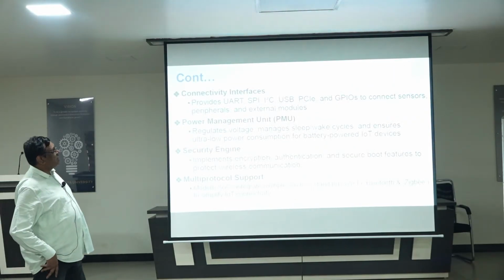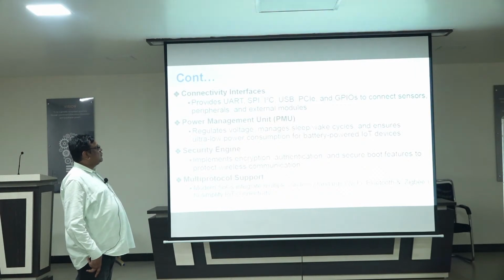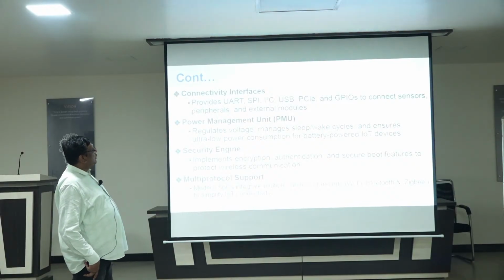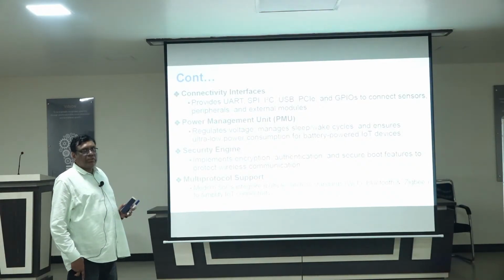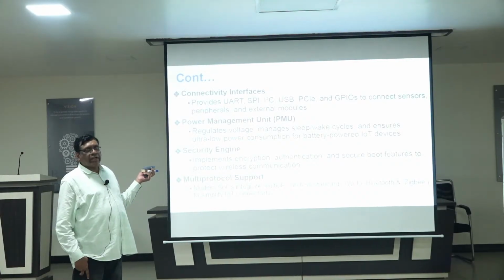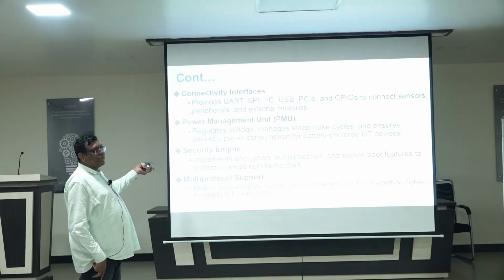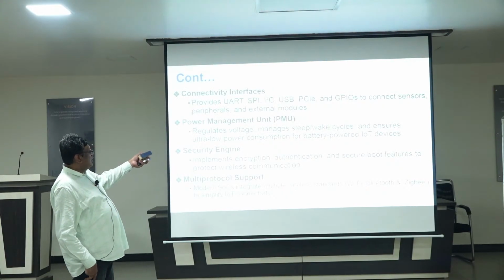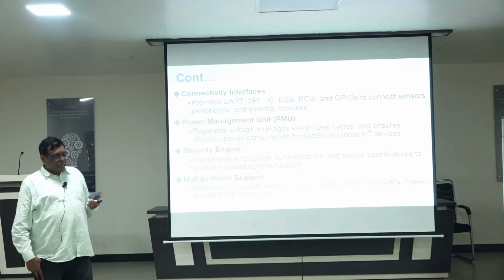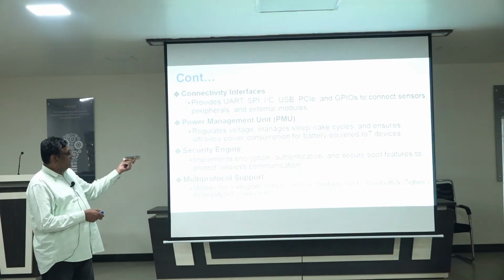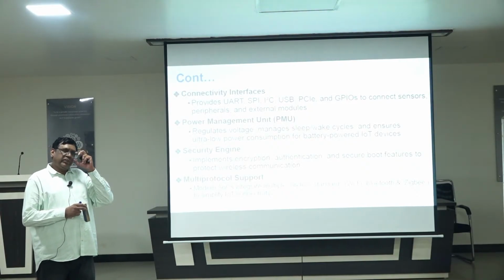Then connectivity interfaces like I2C, UARTs, SPI, PCI Express, PCIe means Express, GPIOs, and power management units, and security engines, especially for cryptography, decryption and encryption of any data. Those types of engines will also be inside any wireless SOC. This security engine is becoming so complex nowadays because of hacking of components. It happens mainly through the security engine only. If the security engine is not proper, you can hack the PC or the hardware.